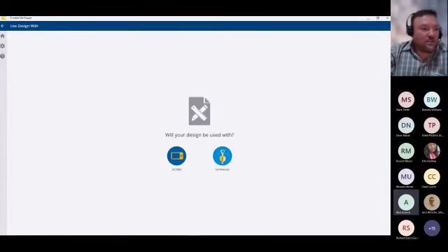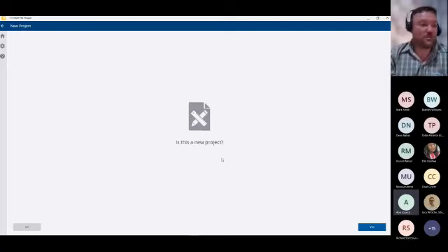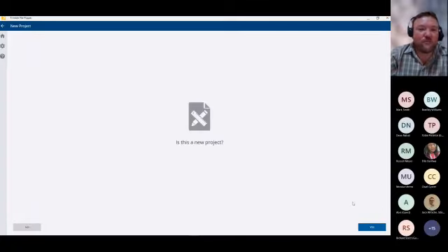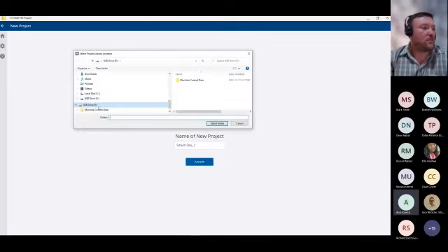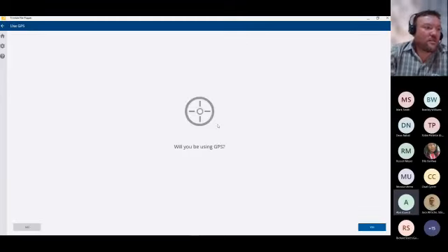Okay, so now I'm going to select my Earthworks machine control system, and it's going to ask me, is this a new project? If you have an existing project running, you can just say no, and you select that folder, that site name, and it will create a file structure within that folder for you for that specific site. Otherwise, just say yes, and I'm going to give it a name. I'm going to call it SiteTech Site 1. Accept it, and I also want to send it to my machine through USB. I'm going to select my USB device, and select the folder.